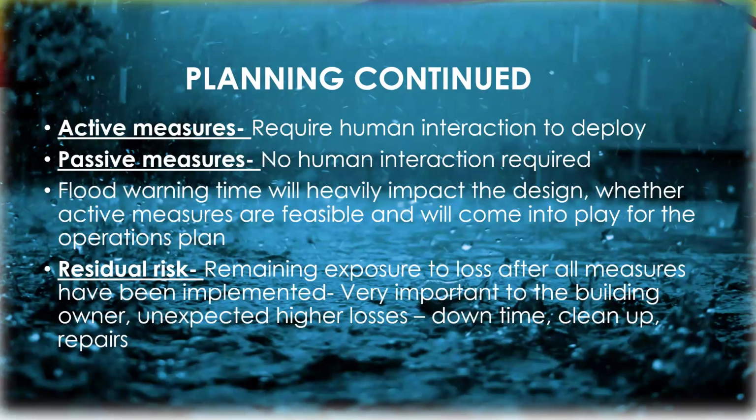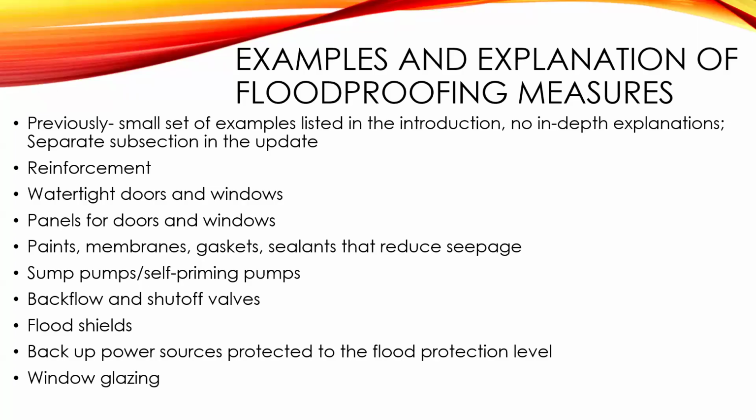plan. So you could have a larger flood than you're expecting, so a higher water level, longer inundation for some reason. The systems can fail, so you'd want to consider what the functional use is of that structure and how, again, the risk would be offset. So failure can be due to unidentified points of entry, poorly maintained measures, insufficient resistance to the flood loads, or failure to implement the active measures. So there's a lot of places where this could go wrong.